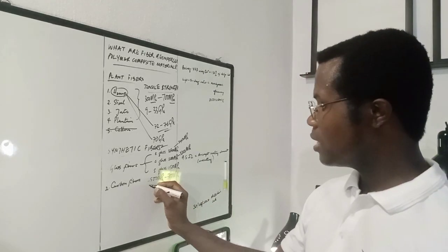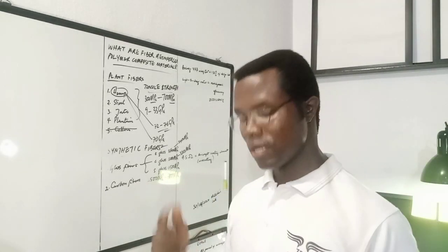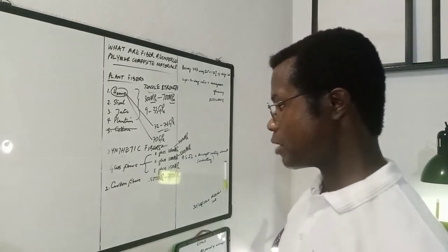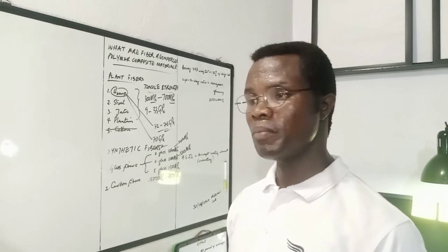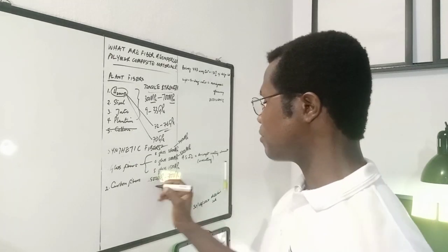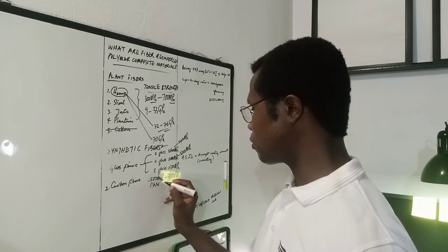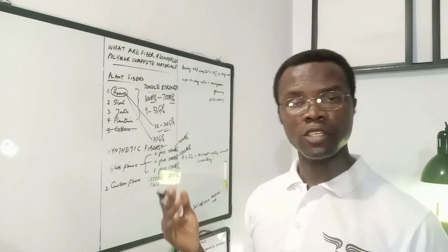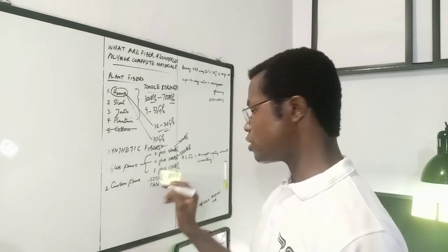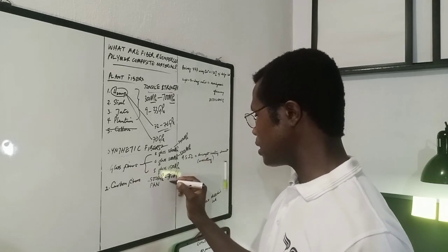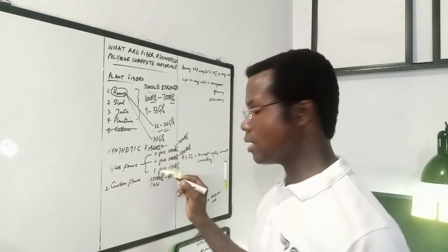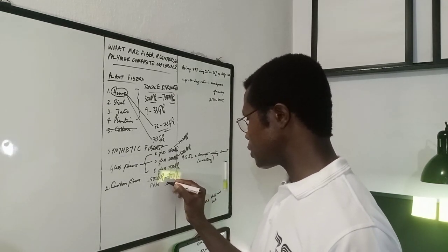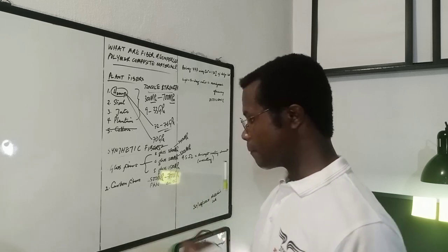Now in general, there is a polymer precursor used in making carbon fibers, which is called polyacrylonitrile, PAN for short. The PAN fibers in general account for the lower end of these numbers, whereas the coal tar precursor, which is also used in making carbon fibers, accounts for the higher end, up to 7,000 megapascals.